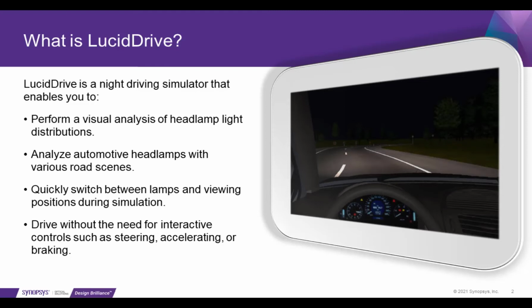LucidDrive complements Lucid shape design tools by enabling you to analyze automotive headlamps with various road scenes. It provides a virtual reality in which to perform simulations prior to expensive fabrication and testing. During a simulation, you can switch quickly between different lamps, viewing positions, road types, and scenes and receive immediate interactive feedback. LucidDrive runs in an automatic driving mode without the need for interactive controls such as steering, accelerating, or braking.